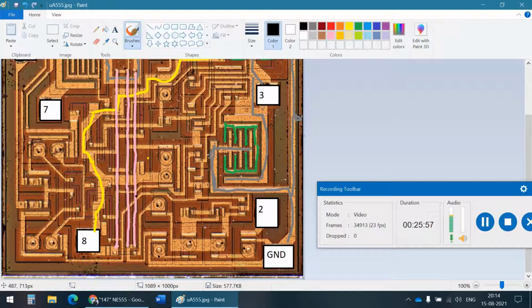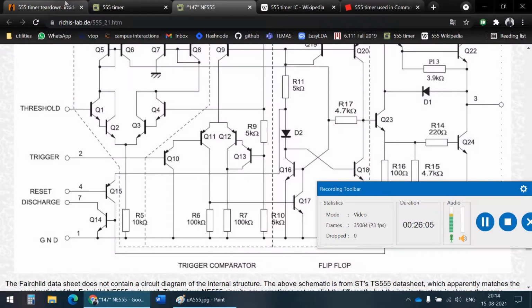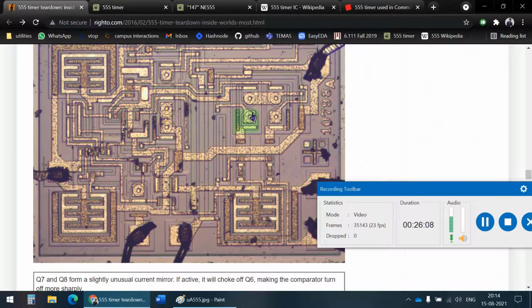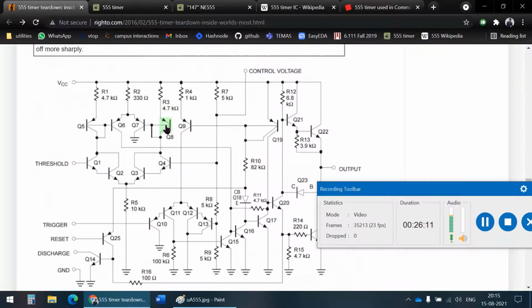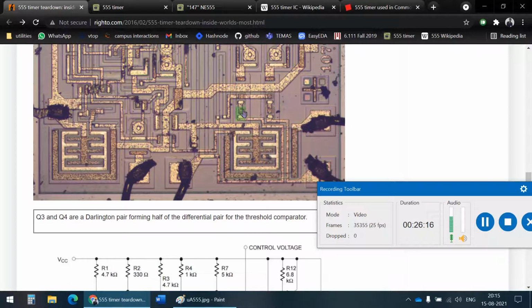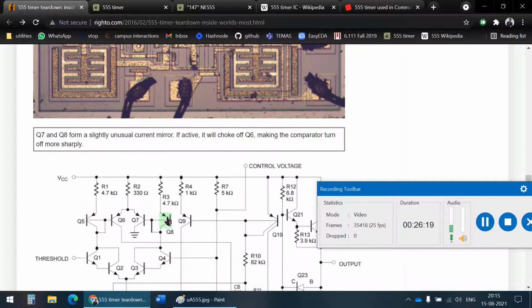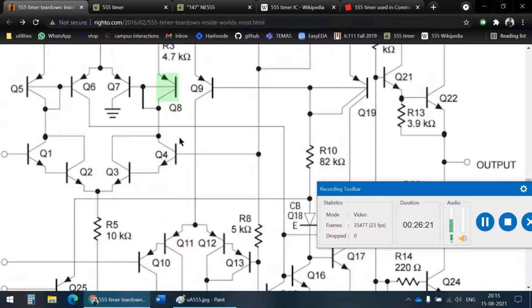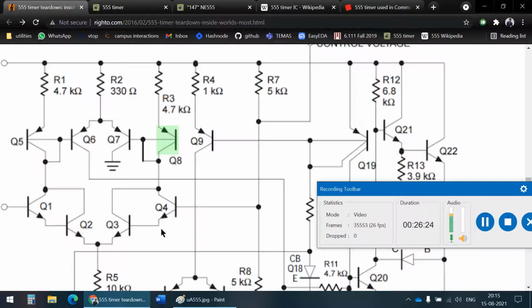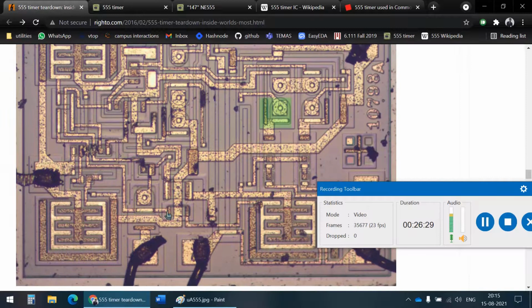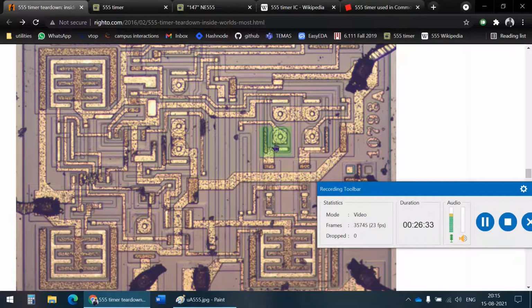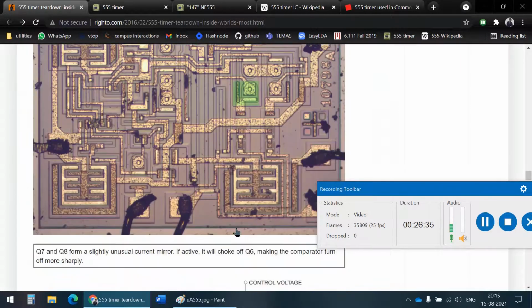These are transistors actually, but how is this transistor different from this or from something like this? Well, these are PNP transistors. So let's go to Ken Sharif's blog and see these. These are PNP, and this here is an NPN. So if you look, that one, that's an NPN. Well, this is a PNP. How do you identify the difference here? An arrow going in is a PNP and an arrow going out is an NPN. The arrow is always on the emitter. P-doped materials are less mobile than n-doped, but yeah, it's not as important.